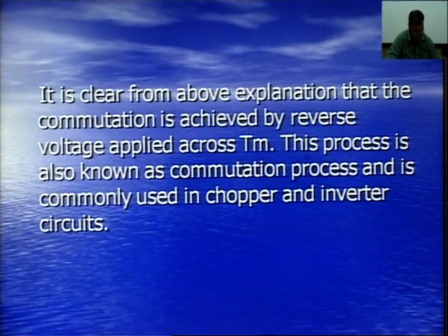If n is the number of thyristors connected in a parallel or series connection, then for parallel connection, string efficiency is equal to the current rating of the whole string divided by n multiplied by the current rating of the individual thyristor. Similarly, for series connection, string efficiency is the voltage rating of the whole string divided by n multiplied by the voltage rating of the individual thyristor. So it is important to note that to obtain the highest string efficiency, all the thyristors in a string must have identical characteristics.